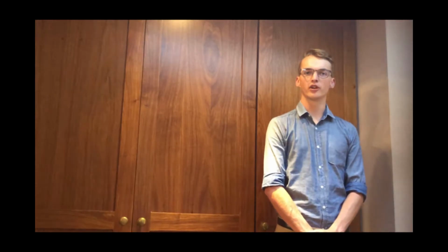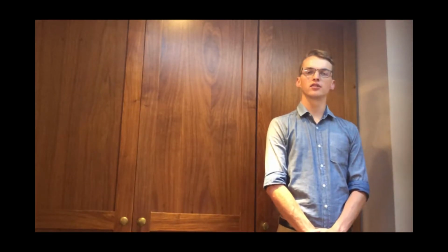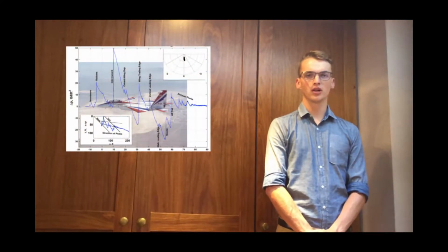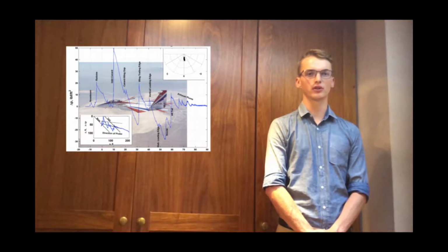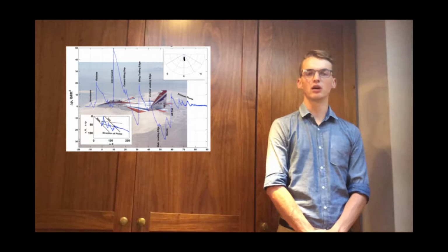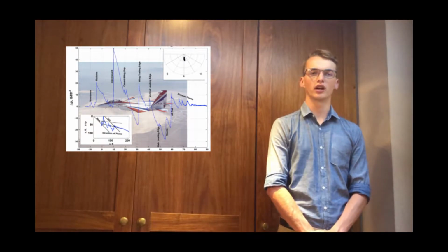Shockwaves around an aircraft body have been of particular interest of late due to the disturbance they cause on the ground, referred to as a sonic boom. There are regulations pertaining to the sonic boom that are currently prohibiting supersonic civil transport over land. Thus, shockwave research is largely into shaping and ultimately reducing the ground shock overpressure signature of an aircraft.